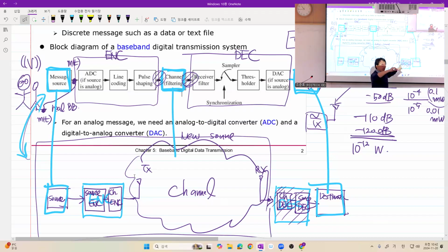And you must have two parallel ADCs perfectly synchronized. Otherwise, you may have a lot of phase difference. As I told you in that two-pass model, a slight timing difference may give us totally rotated phase. So for a full digital RF system, you need very accurate, perfectly synchronized DACs and ADCs. And actually, that's the task right now. We want to convert as many parts of our radio equipment as possible to digital parts. And we need very fast, perfectly synchronized, very small error ADCs and DACs.